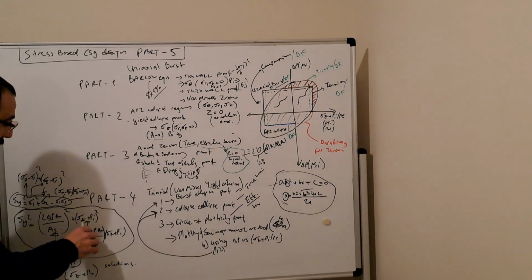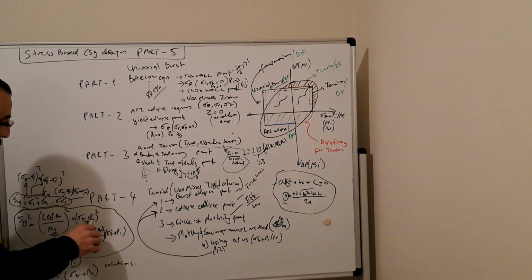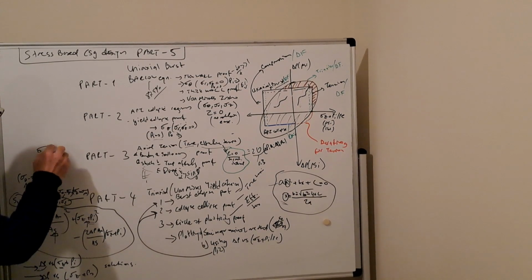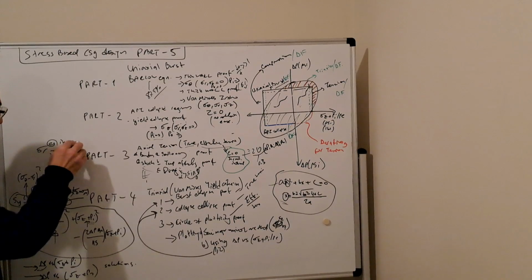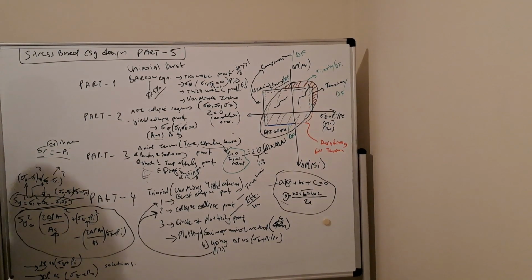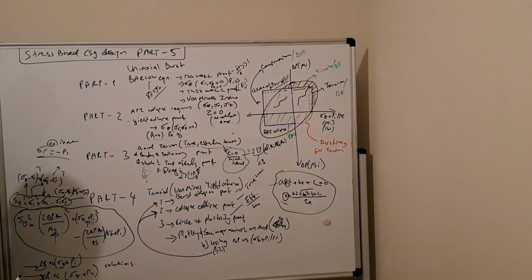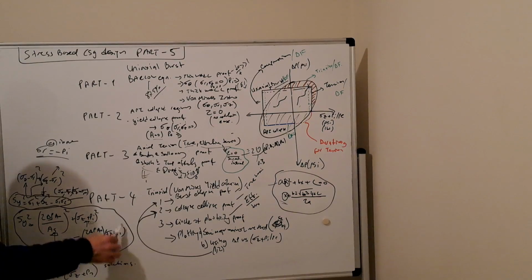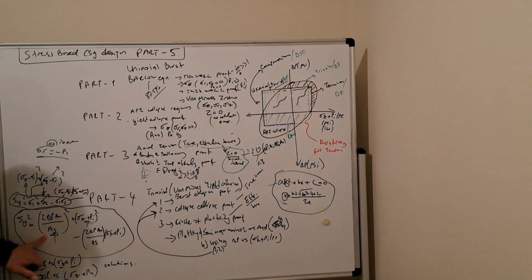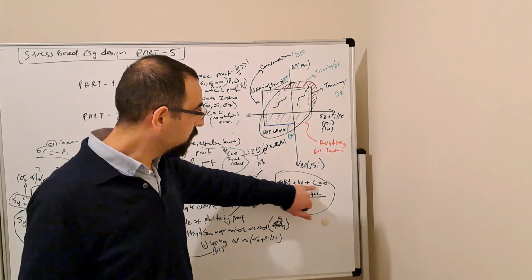We take the difference between the axial and the radial stresses at the inner wall, and this simply transforms into axial stress plus the internal pressure, because we know that the radial stress at the inner wall is minus the internal pressure. This is regardless of the pressures in the inner area or outer area, or regardless of anything. So we came up with this simple equation, and we know that for a quadratic equation like this one, ax squared plus bx plus c,